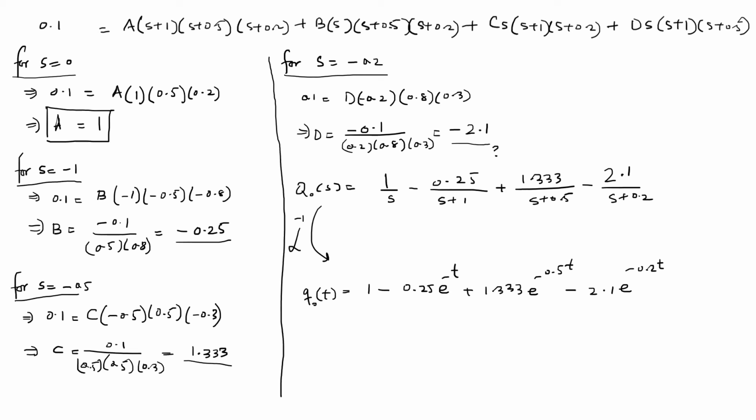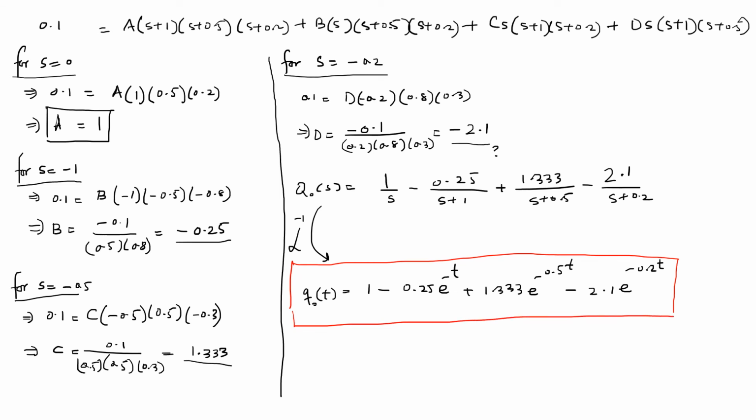So that's what your outflow equation is going to be when you have a three-tank system defined with those parameters that we have defined corresponding to the areas of the tanks, the density of the fluid, the G, and the resistance out of the valve. So with this realization, you have got the expression which defines the flow out from the output tank.